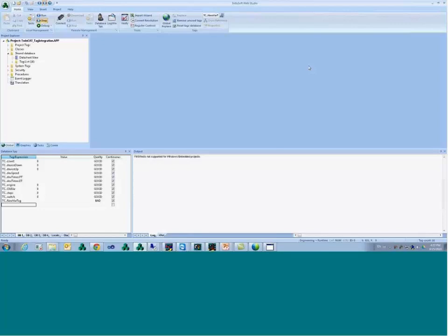All right? And when would I use OPC in that case? When would I rather use OPC instead of the driver? There are some situations where you may want to have several HMIs talking to the same PLC. You're going to be bombarding the PLC with data. If you have an OPC server, the PLC can focus on running, and the OPC server is going to focus on the communication as well. That's one option. And if you want to have more security than what can be offered in the communication between InduSoft and the ADS, you can use the OPC UA as well.